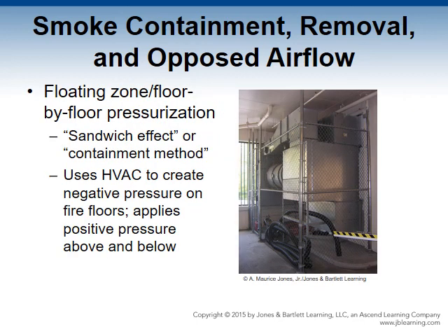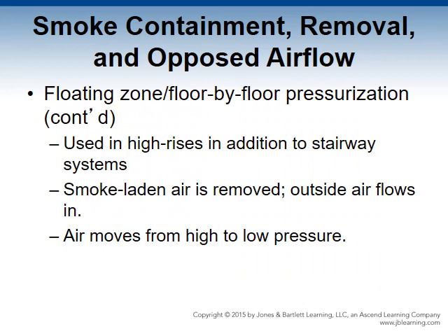Floating zone floor-by-floor pressurization, also known as the sandwich effect or containment method, uses the basic components of an HVAC system to create negative pressure on the fire floors while applying a positive pressure above and below. These systems may be used in high-rises in addition to stairway